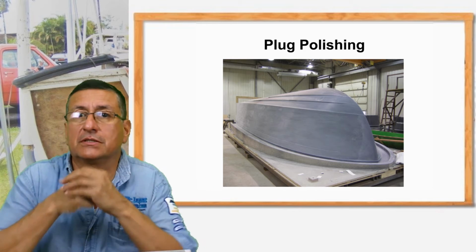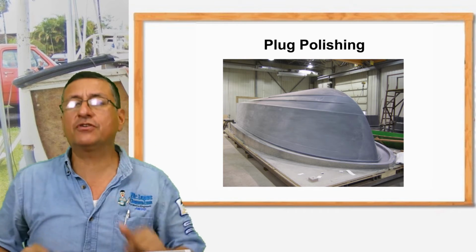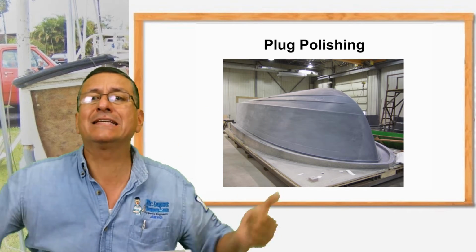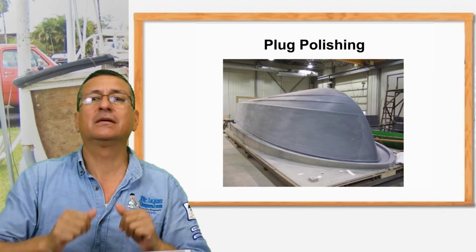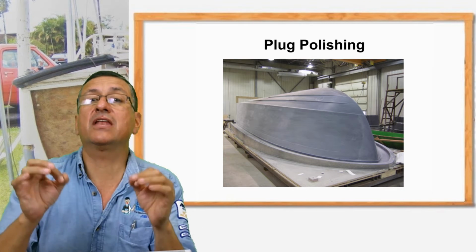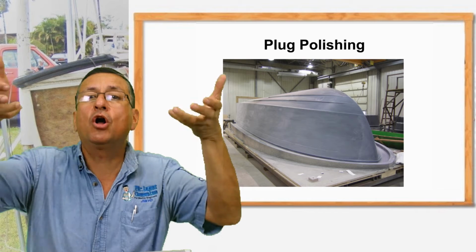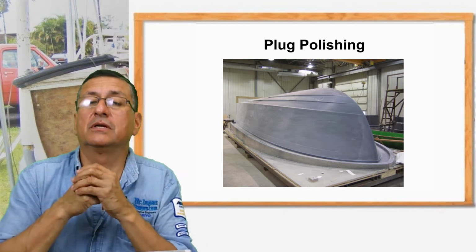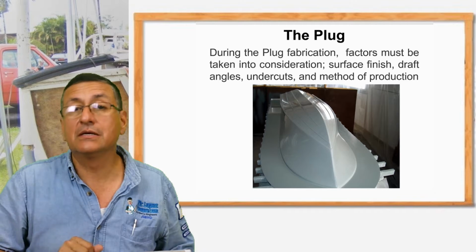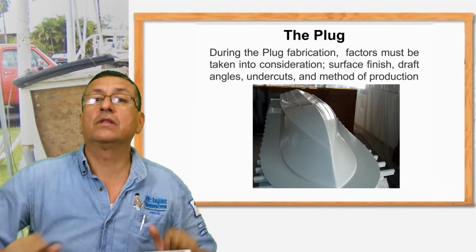This is the process. When the block is properly finished with the angles, this is the most important part. The block needs perfect angles in order to remove the mold easily. If the angles are straight, removing the mold after that is not possible. The secret in the design of the block is the angles, the inclinations, in order to release the mold easily. This is part of the creation, this is part of the design. Yes, this is the most important part, the angles like this, because after that, when you cover it with fiberglass and gel coat, it's easy to remove the mold.